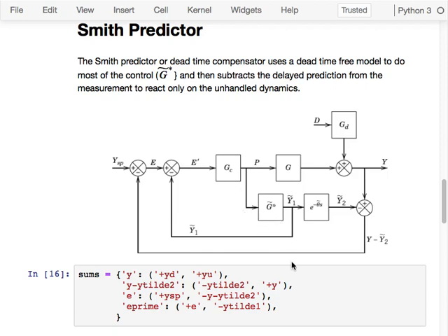It's based on this idea that maybe the problem with the dead time is from perhaps just a very poorly functioning measuring instrument, or a slow measuring instrument. The classic slow instrument is something like a GC, where you're taking a sample and it's taking 5 minutes to go through the column. Even if you're doing a continuous GC, you have to actually wait for the stuff to travel down the column to settle. There's no sidestepping that. So maybe it's taking a very long time to actually get the measurement out.